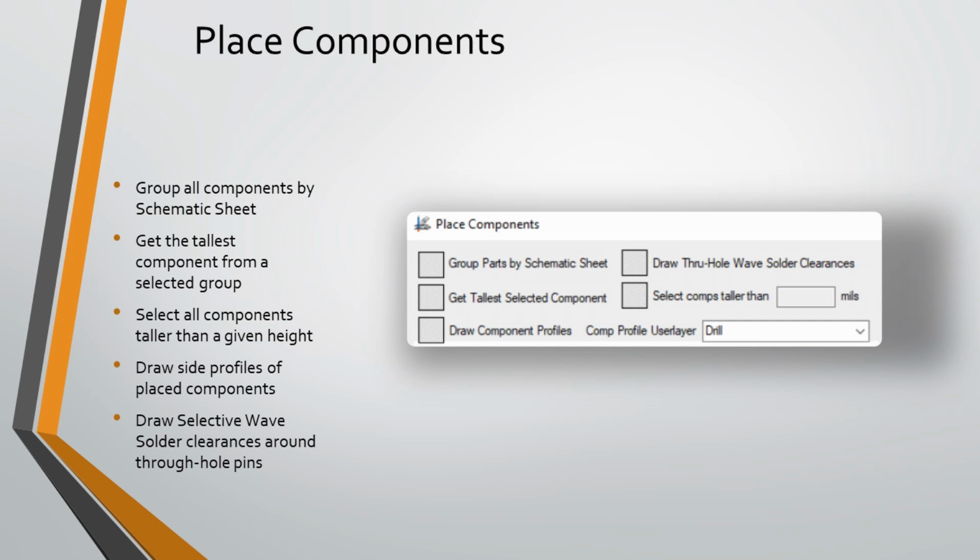The designer is then faced with the task of placing each part in the circuit it belongs to. Cross-probing the schematic can make this process easier and faster. However, there is still a lot of time and effort wasted selecting and moving parts into groups just so that they can be close enough together to start forming the circuits.